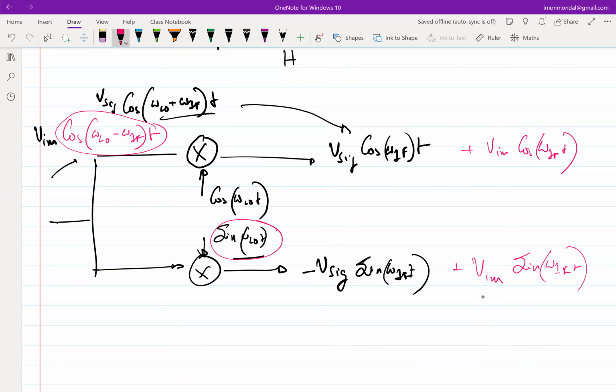And that is a significant difference, because a 90-degree phase shift is essentially a quarter cycle delay. For any frequency, when I say I am doing a 90-degree phase shift, I am moving the sinusoid by a quarter cycle. Full cycle is 360, half cycle is 180, quarter cycle is 90. Designing a delay at high frequency, just like anything else, is a difficult job, but designing a delay at low frequency is a much easier job.